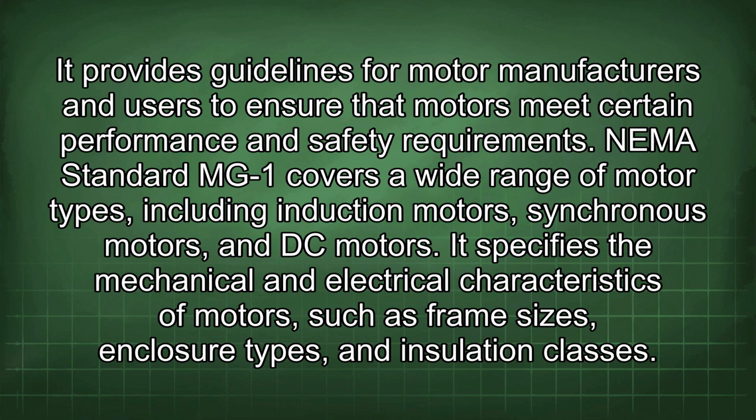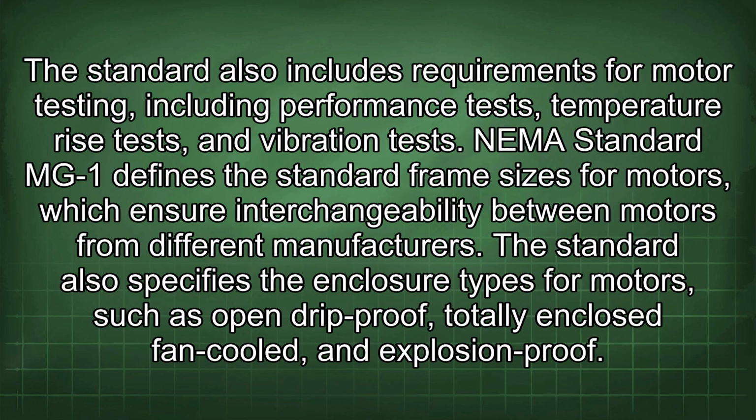It provides guidelines for motor manufacturers and users to ensure that motors meet certain performance and safety requirements. NEMA Standard MG-1 covers a wide range of motor types, including induction motors, synchronous motors, and DC motors. It specifies the mechanical and electrical characteristics of motors, such as frame sizes, enclosure types, and installation classes. The standard also includes requirements for motor testing, including performance tests, temperature rise tests, and vibration tests.